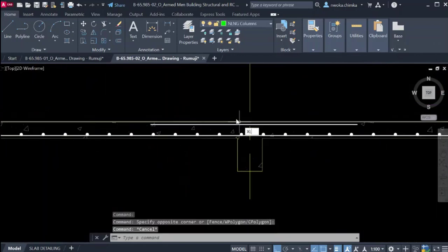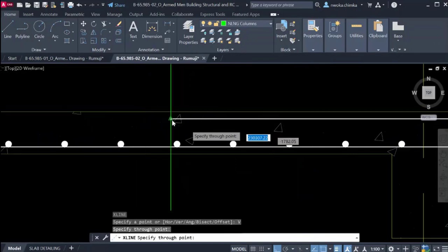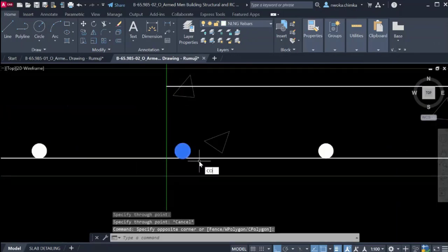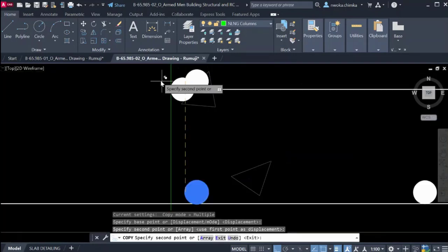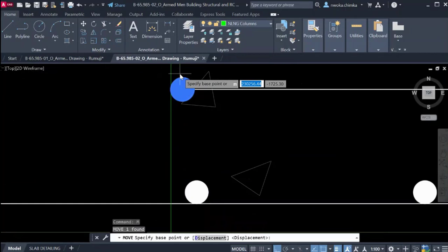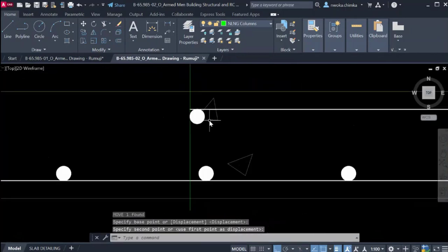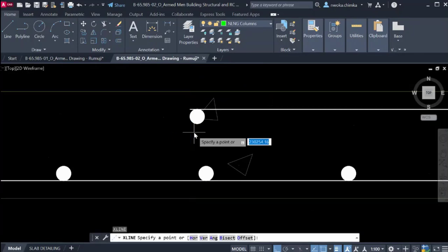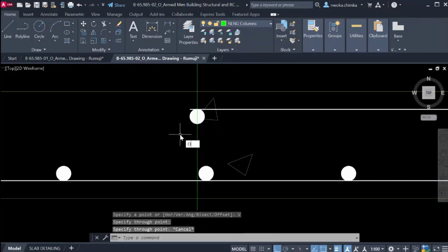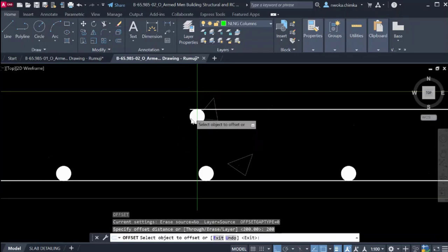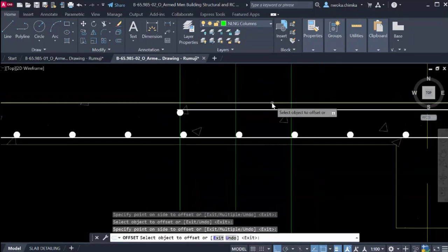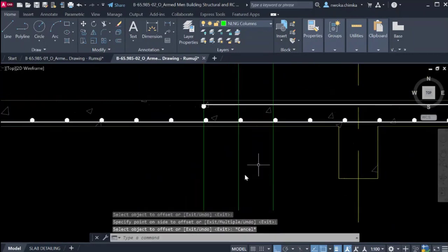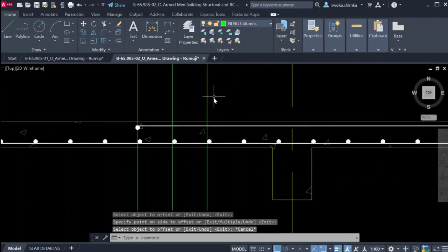So we also use construction line V, align this point on this area, copy one of these dots, since they are the same reinforcement sizes, paste it here and then bring it down here, and then remove this construction line. Create another construction line again, and put it at the midpoint using the spacing of 200, which is from the design report, going all the way down. Let me show you the design report, or maybe I'll show you the design report after.